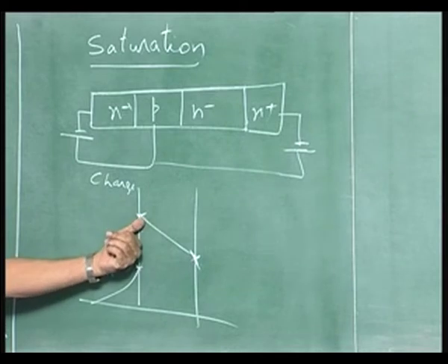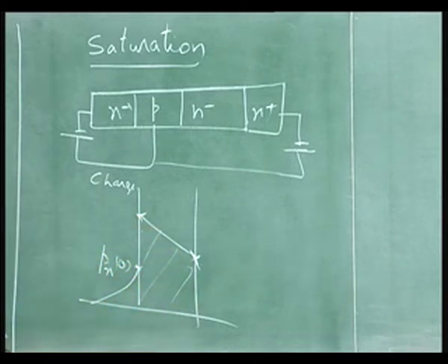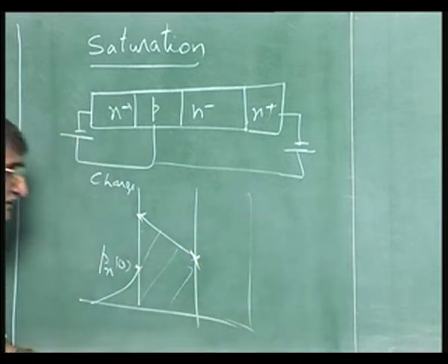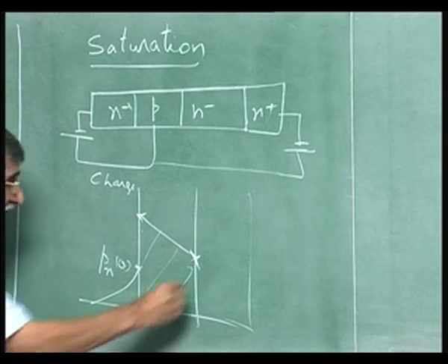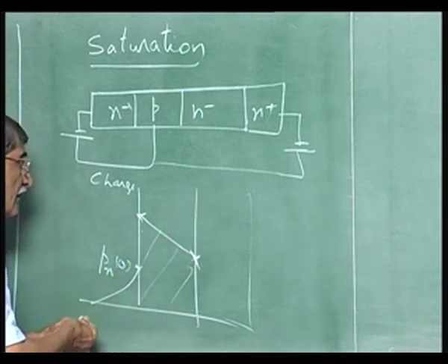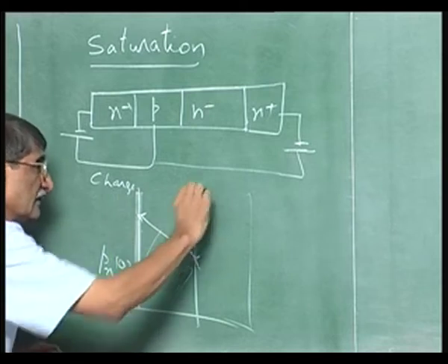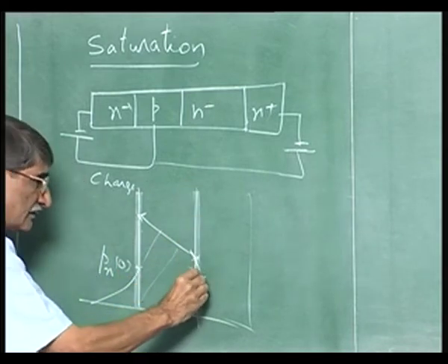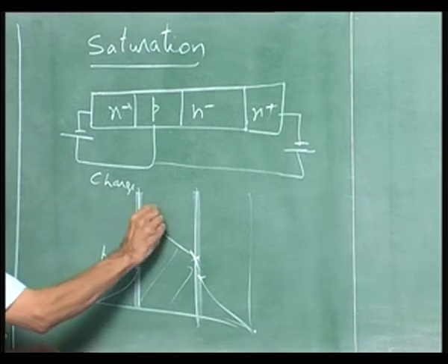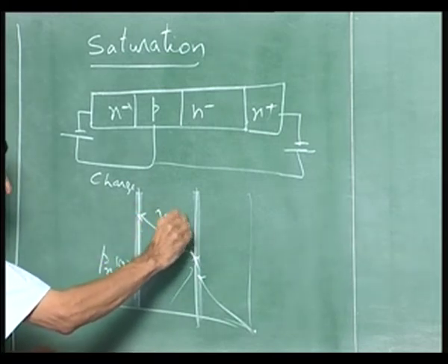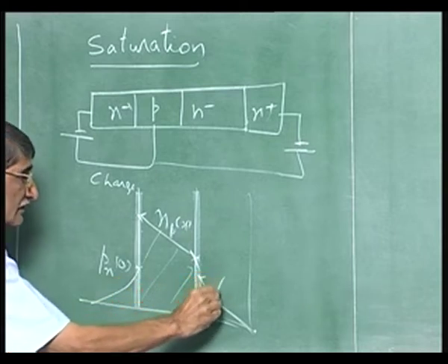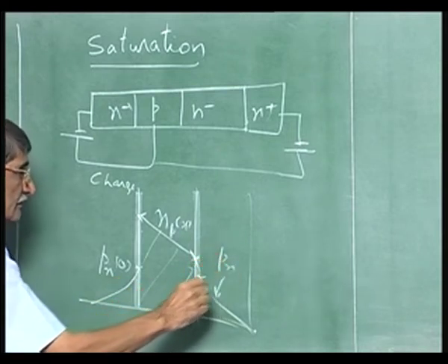But there is a tremendous amount of charge here. If it goes into saturation, to remove the charge, you must pump out the charge from that base region by reverse draw of the current in the base. What about here? When forward biased, the same is here also. I have a small transition region in all the cases, of course, which I have not shown here. Then from there, this is np of x, pn of x, and this is pn.